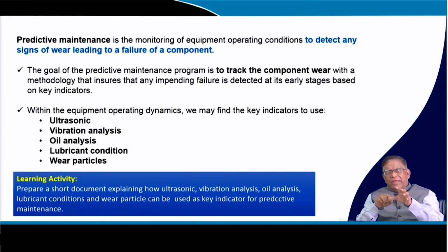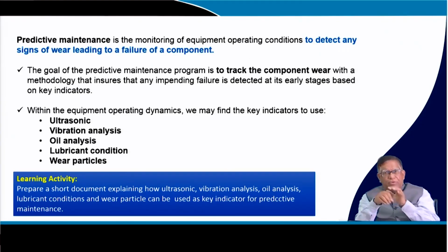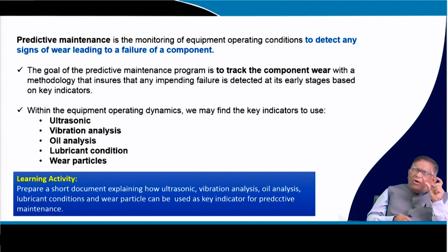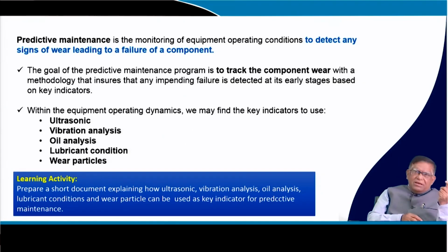You can use it in your gearbox to check whether the oil is dirty or working properly. You send in a tube with an optical fiber, illuminate it, take a scan and find out. Like that, you can enter the gearbox and see inside. Similarly, you can use ultrasonic, high frequency acoustic waves, to find out how it is working. Vibration analysis is done. Oil is the heart of any machine, just like the blood in our body.